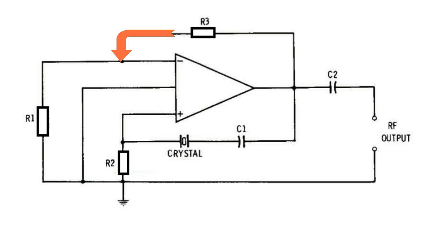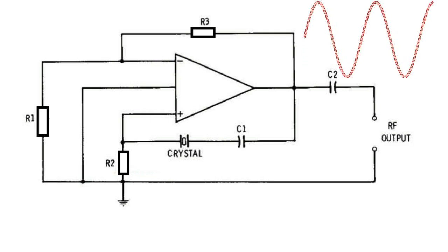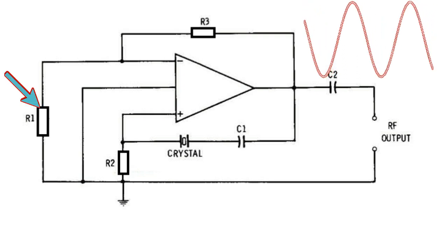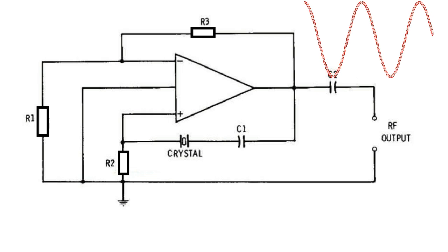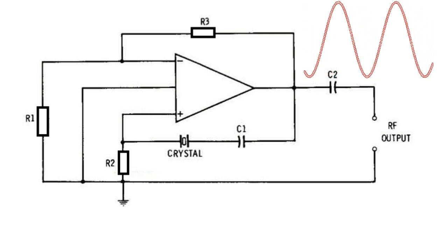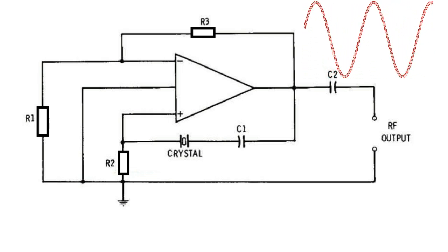Negative feedback current flowing by means of this resistive divider causes a voltage drop to appear across resistor R1, which is supplied to the op-amp's inverting input pin. It may be important to adjust the amplitude of this voltage by appropriately setting up the values of the resistors R1 and R3. This ensures that the positive feedback does not get terminated, eventually killing the oscillation.